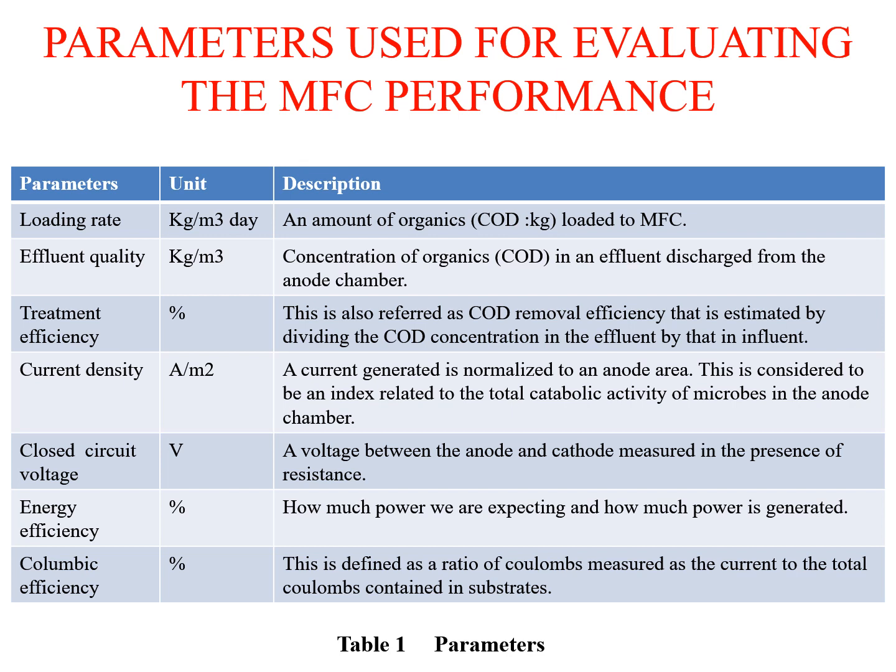Let us see some parameters used for evaluating MFC performance. Loading rate. Its unit is kg per meter cube day. It is the amount of organics in kgs loaded to the MFC. Effluent quality. Its unit is kg per meter cube. It is the concentration of the organics in the effluent discharged from the anode chamber.